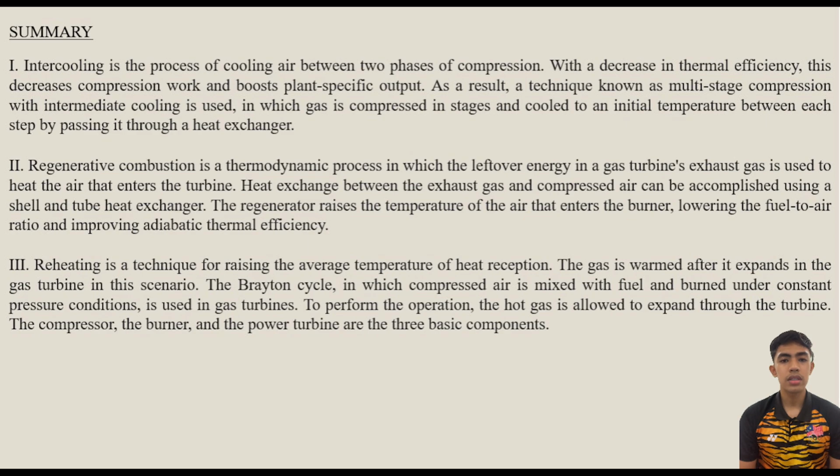In the Brayton cycle, compressed air is mixed with fuel and burned under constant pressure conditions. It is used in a gas turbine to perform the operation. The hot gas is allowed to expand through the turbine. The compressor, the burner, and the power turbine are the basic components.